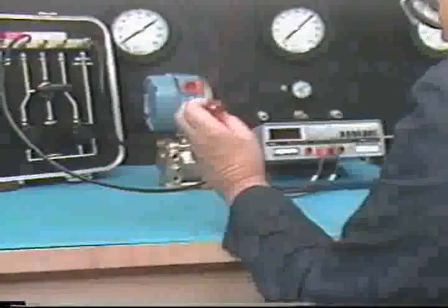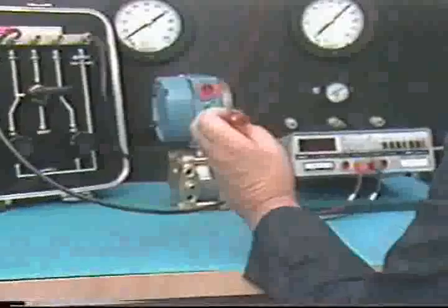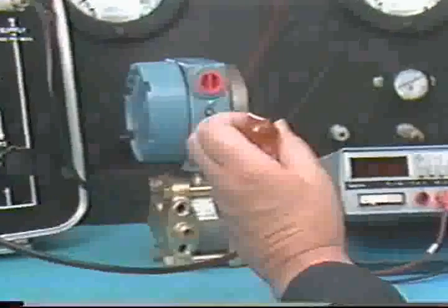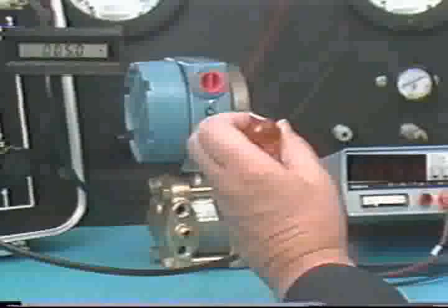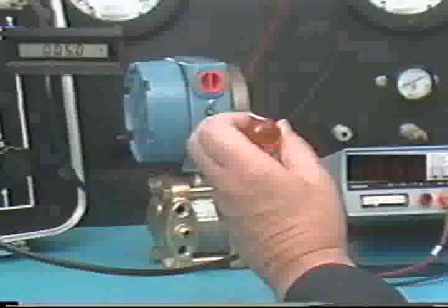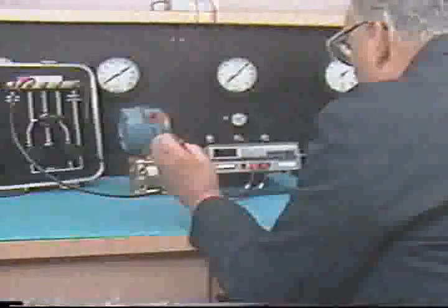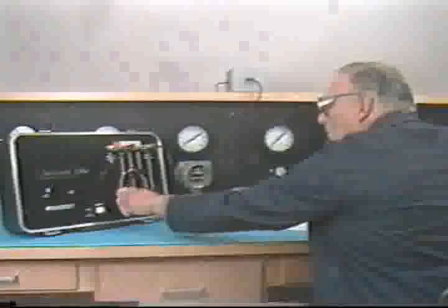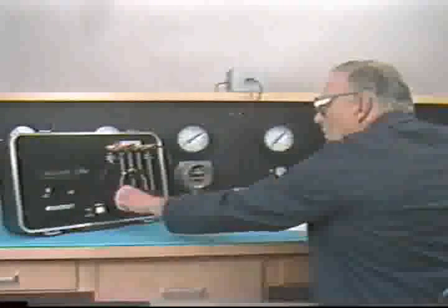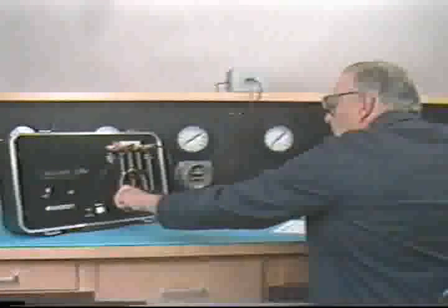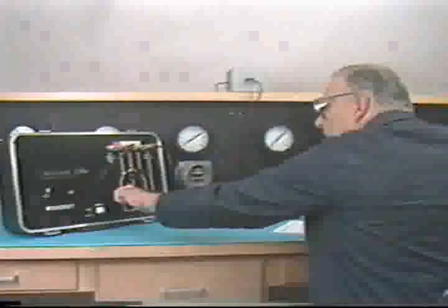Typically, when an instrument is calibrated, the zero is adjusted first. That's because to adjust span, you need an accurate base point, or zero. Zero should be adjusted so that for a 10% input, a 10% output is displayed. Once zero has been adjusted, span should also be adjusted. Since zero and span frequently interact, after one of these errors has been corrected, the other may require readjustment. A 5-point check will verify the accuracy of the calibration.